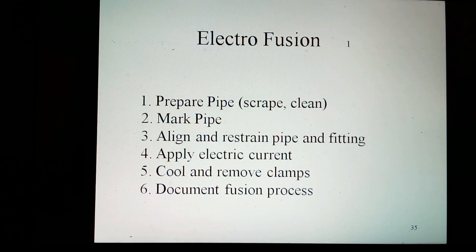Next, the pipe surface for fusion must be scraped, that is, material must be removed to expose clean, rigid material. This may be achieved by various special purpose tools available from the fitting manufacturer. Step 2. Mark the pipe for stab depth or cut under the proper fusion location with saddles. Caution should be taken to ensure that a non-petroleum marker is used.